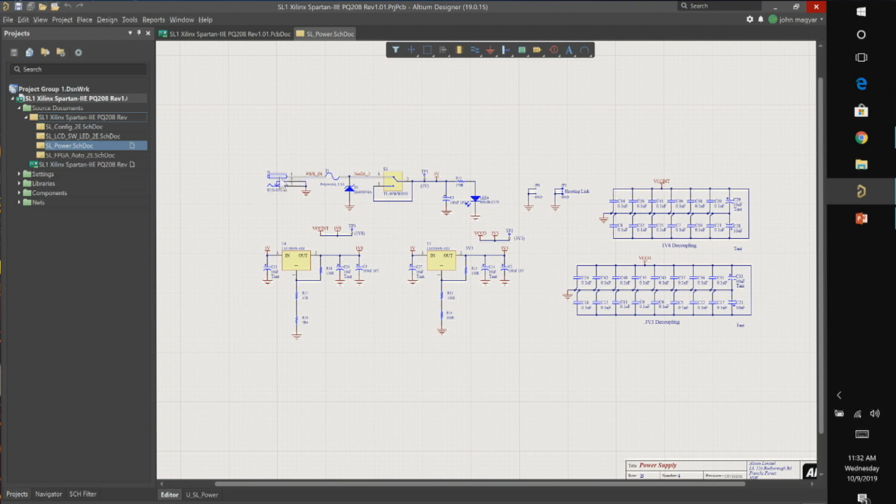supply voltage coming in. That's 5 volts DC, and very simply a 3.3 volt generation through a linear voltage regulator, and likewise a 1.8 level voltage for inside of an FPGA. So that's the internal core working voltage, and then the 3.3 is the I/O of most of the devices, and then there's a typical 5 volt level for some older components. So pretty much what you would see in designs, but you can get designs with dozens of DC voltage levels, and that is fairly common.